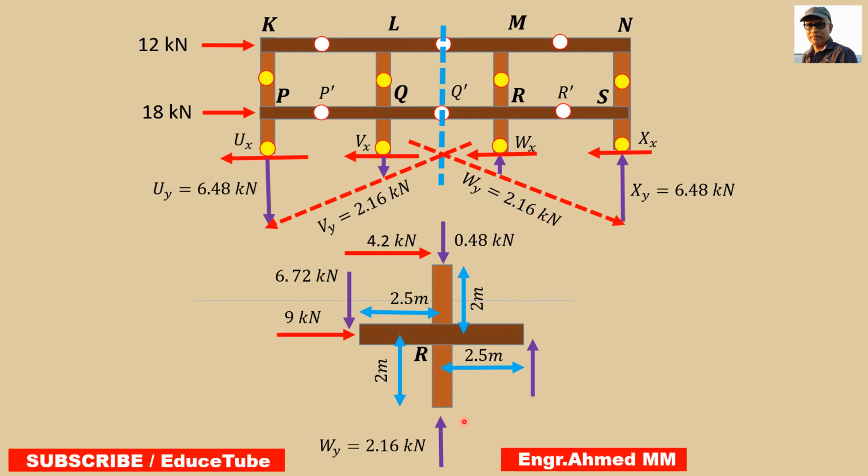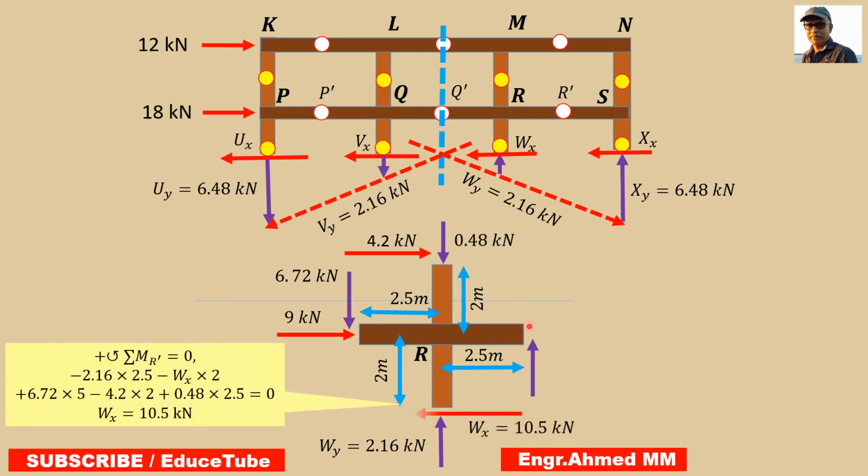Now we need to get horizontal. Horizontal means we have to take the moment about this point, including all these forces: 2.16, 2.5, 6.72 multiplied by 5, 4.2 by 2 and 0.48 multiplied by 2.5. So we got 10.5 Wx. So this is the horizontal component of this point.